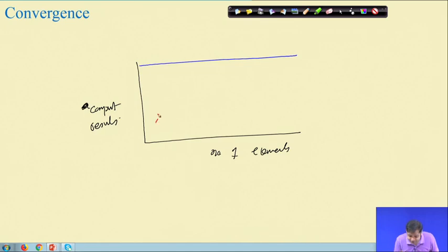And if you increase the number of elements, you are slowly increasing the degrees of freedom. You are making this structure go from stiffer to stiff, and then more flexible, then more flexible. So, this will converge to this. This is a typical characteristic of convergence in the finite element method. So, it is always bounded from the top. Okay. So, this is the way we get the convergence for the displacement. We won't get the convergence in any haphazard way.